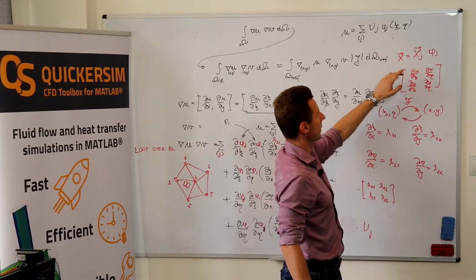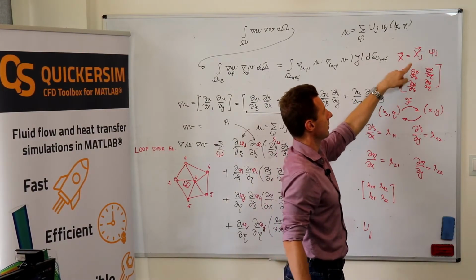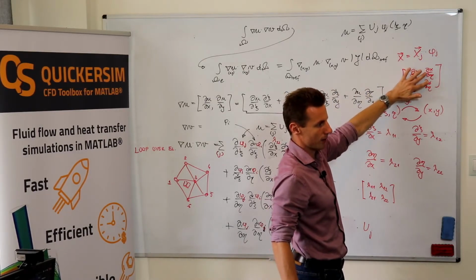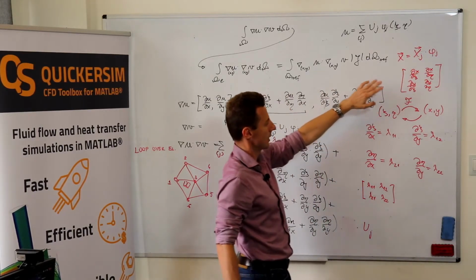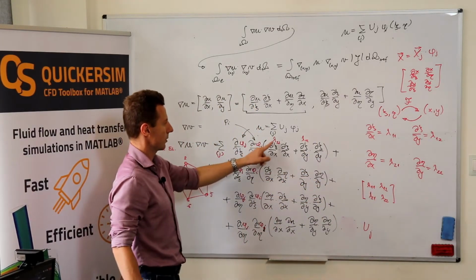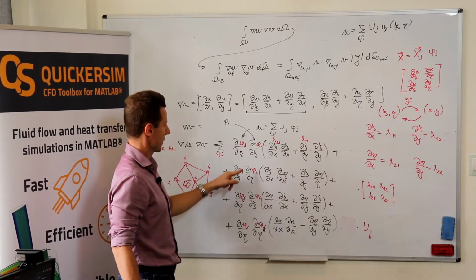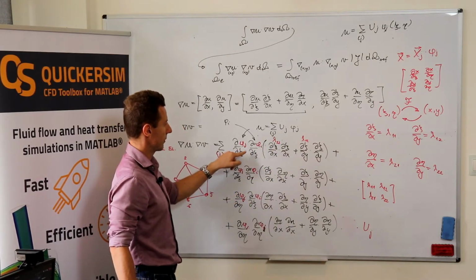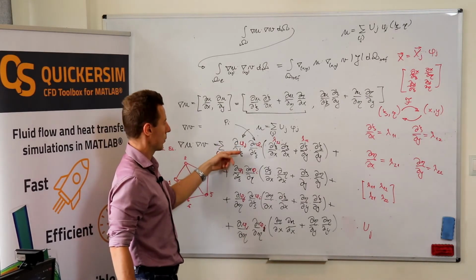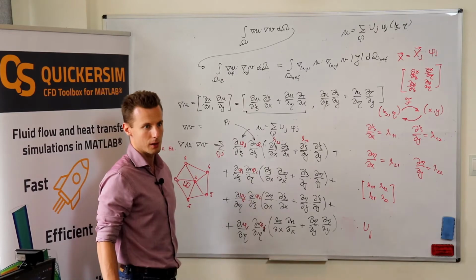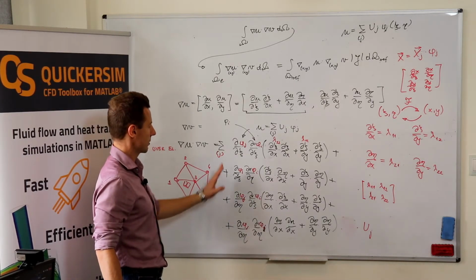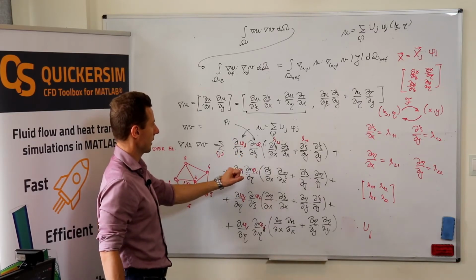So you can differentiate that with respect to psi and eta. Then you arrive at the Jacobi matrix. Then you calculate the inverse of the Jacobi matrix. So you got all these lambdas. These derivatives are no problem because these are derivatives of the shape or test functions with respect to their natural arguments. So you can calculate everything like that.